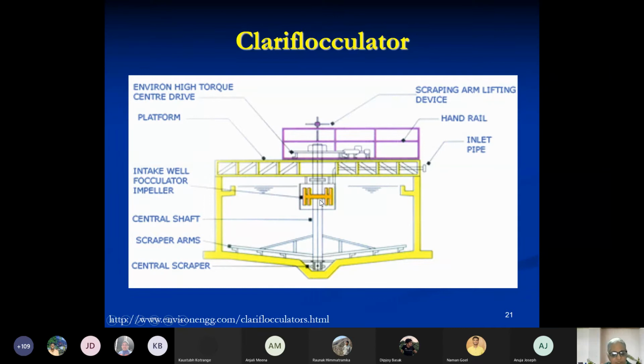So these paddles are rotating very, very slowly, a few millimeters per minute, you might say. Okay, so it's a very gentle process, and the only thing that this wall does, it's literally like a suspended wall. What this wall does is it separates the flocculation tank from the settling tank. This area is the settling tank, and the volume in the center is the flocculation part of it.